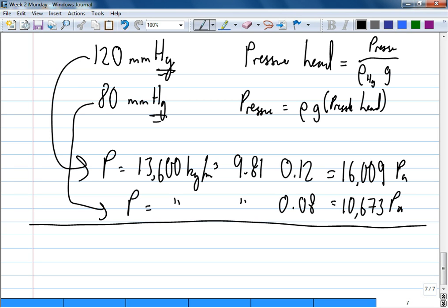This is the mains pipe that comes to your house. What you do in your house is your business. Normally you can get about 4 atmosphere, 4 bar like that, between say 3, 4 up to 5. I don't find it very high. Between 3, 4, 5 bar.